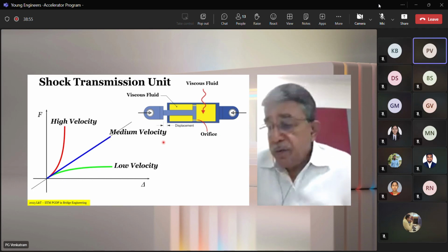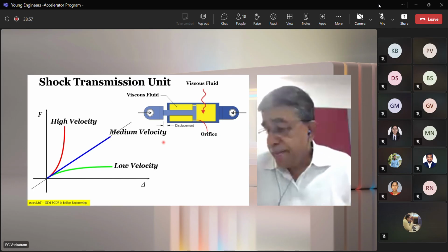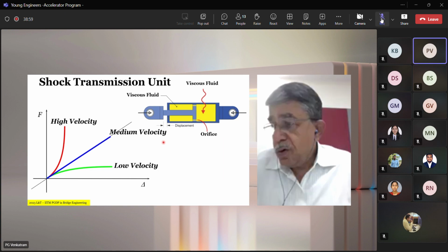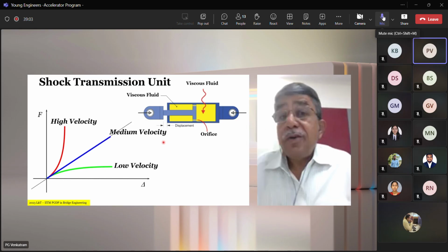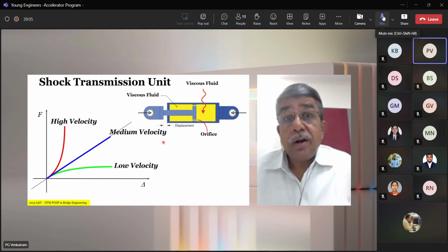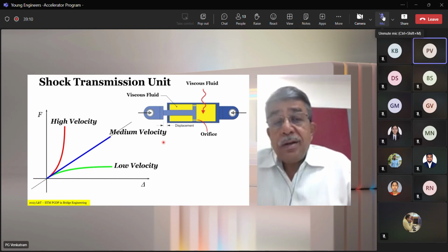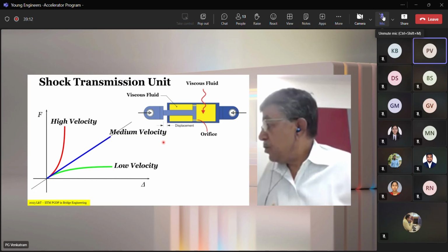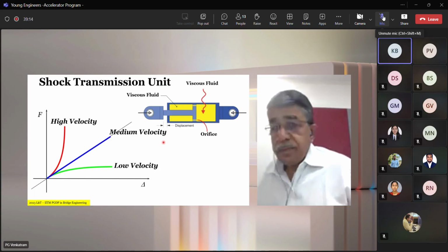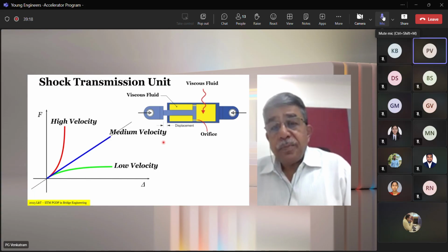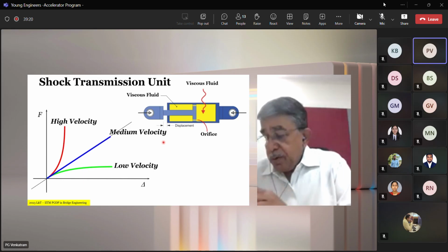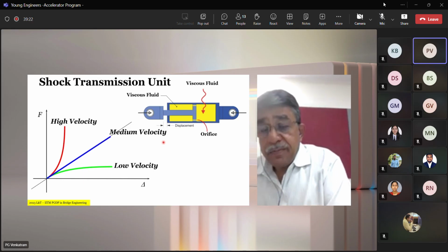All the inertial forces will go to what? To which foundation? If it's a long continuous structure and it has one fixed pier, all the longitudinal inertial force will go to which foundation? The fixed pier. Exactly, to the fixed pier. Now, what will happen to the design of the fixed pier and foundation?